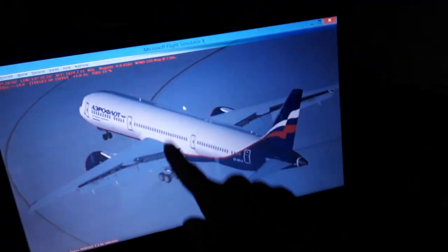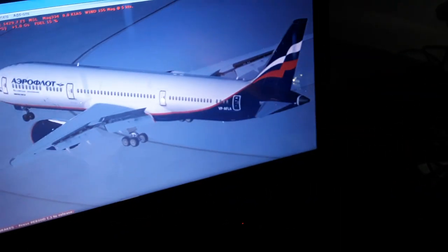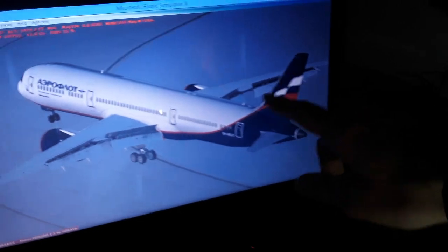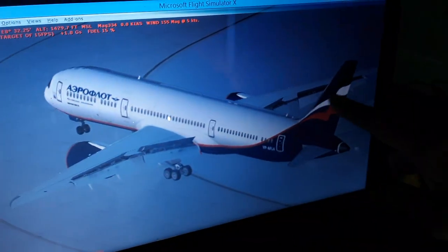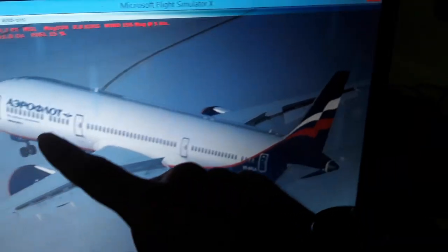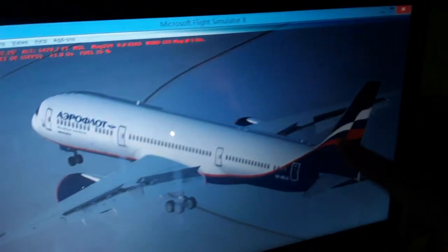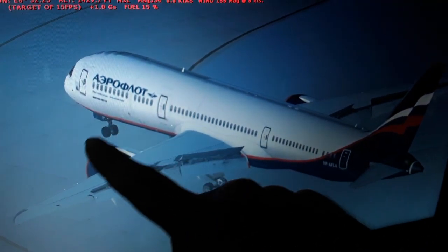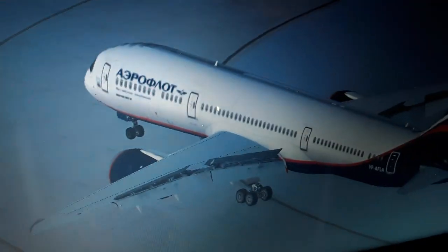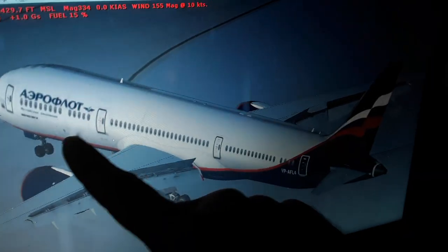Also the center of gravity is the yaw axis. We use the rudder to make left and right turns like this, as you can see. The rudder pedals control, and we have also the nose wheel simultaneously. When we fly, we have only the rudder. When we are on the ground, we have both the rudder and the nose wheel to make left and right turns until some airspeed from 0 knots up to 45 knots or 72 kilometers an hour. We can use the left and the right turn on the nose wheel automatically from the computer when we press the rudder pedals up to 76 degrees left and right turn.